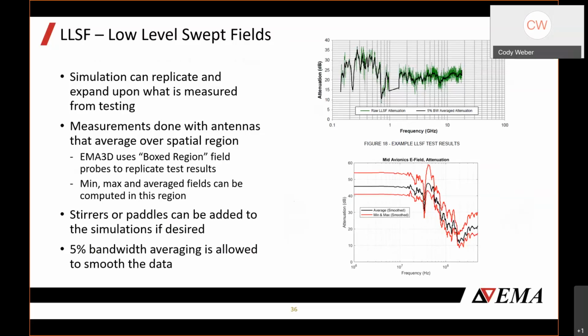So the spatial averaging associated with the testing is important to consider when you're doing this field capture in your simulation models. It may be appropriate to do all of your plots in this nature, where you're showing a min-max and an average. And really what we find to be the best is using that average value for your comparison to testing.